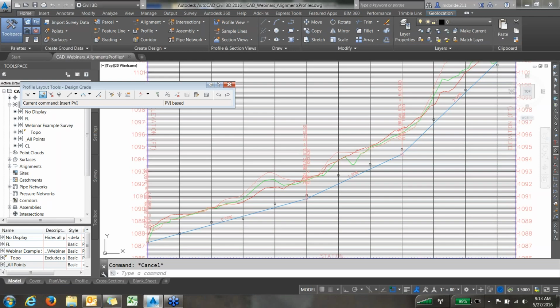The next step, which will be the next webinar or two, will be to physically cut in the shape of your grass waterway. After you have it designed, say it's 40 foot wide, 1.5 foot deep, you'll physically cut it into the surface using this grade. So all this will fall in line. We just haven't got to that point yet. So if this seems kind of odd, like, well, this didn't give me a cross section yet, well, we're not there yet. So hopefully this will at least give you a good idea how to do a profile. And you can use this process, if maybe not for grass waterways, for, say, a subsurface drainage tile as well. So there's multiple things you can be doing.